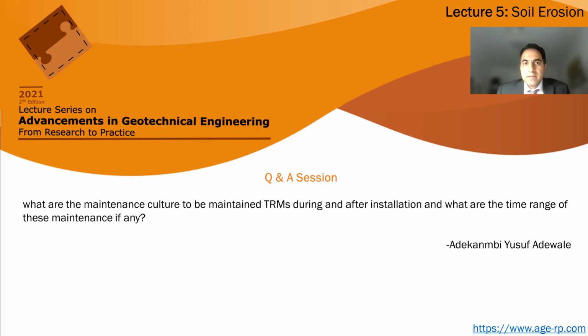But the main maintenance is mowing the vegetation. When you have vegetation, you want to have mowing, and it depends on the type of vegetation you have. That's why in Colorado, in the US Army test, they tested for real mowing loads. There's a parameter called resiliency. Resiliency is the property of TRM or HPTRM that takes care of the mowing and all these loads. So the TRM should have a high resiliency.